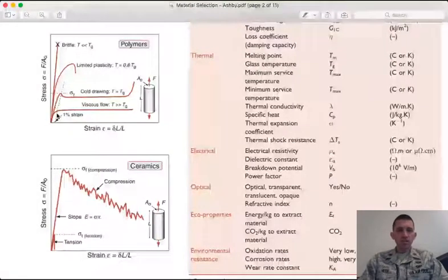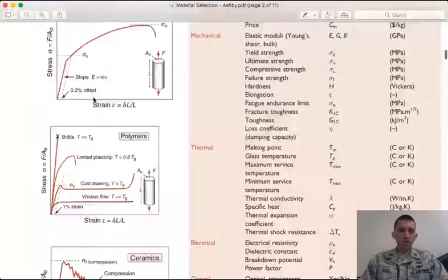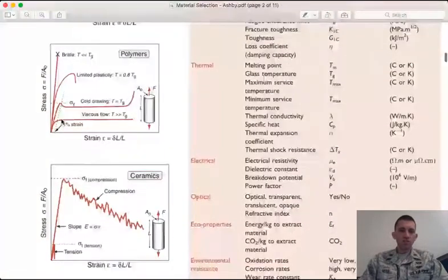We see this in polymers, that there's a wide range of mechanical behavior, ranging from very brittle polymers to very ductile polymers, and everywhere in between, right? And so you have a wide range of ductilities in metals also, but polymers are distinguished by the fact that you can get a very drastic change in mechanical properties over a relatively narrow temperature difference.